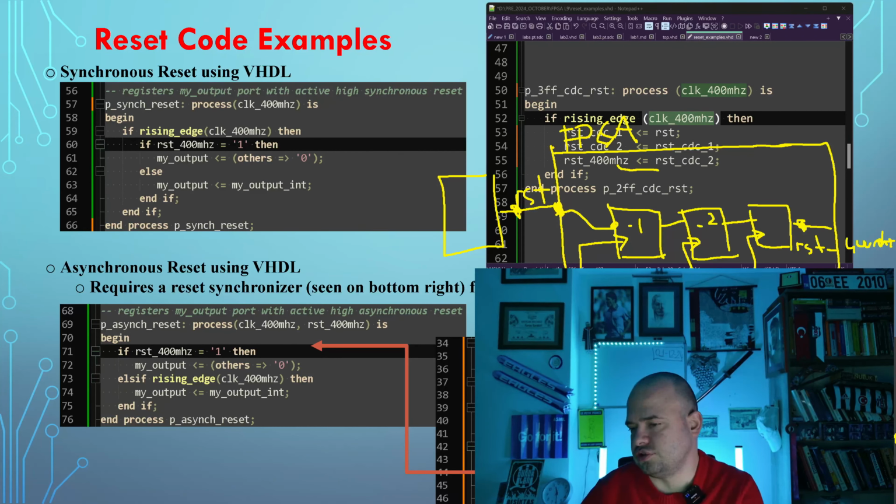Again, if your FPGA family is an old one, and by the way, if it is too old, it won't be possible to use a 400 MHz clock anyway. For that FPGA, if the tool cannot provide any positive slack for 400 MHz, you won't use it anyway.